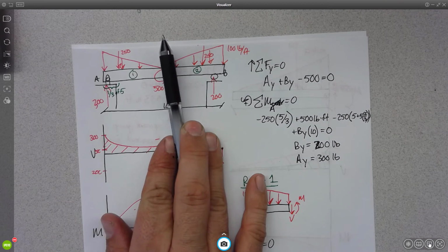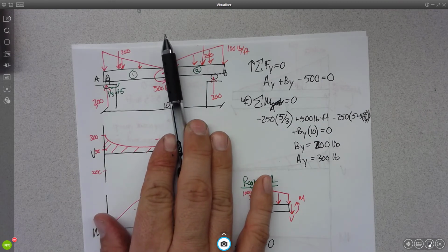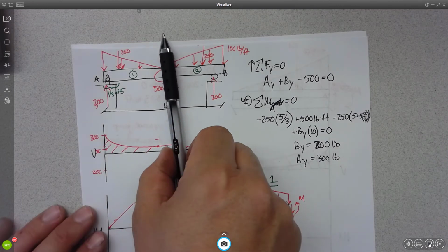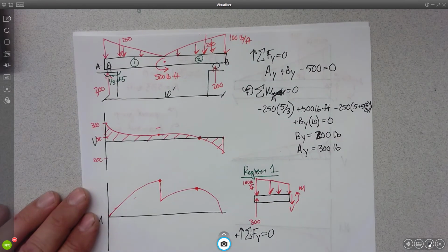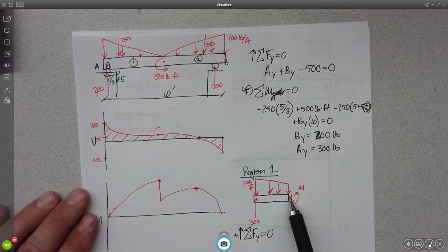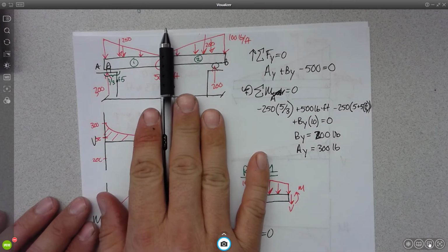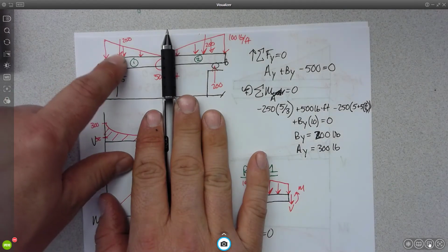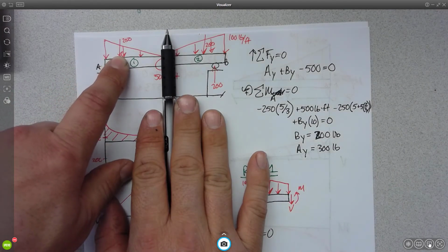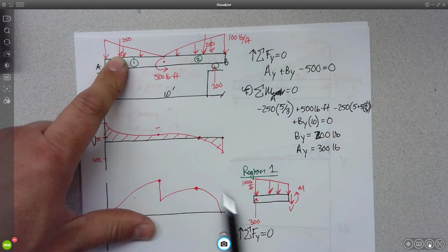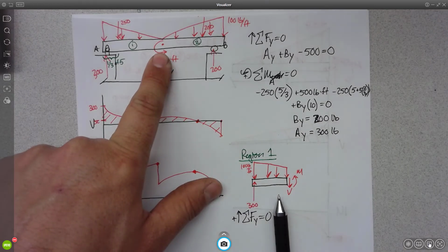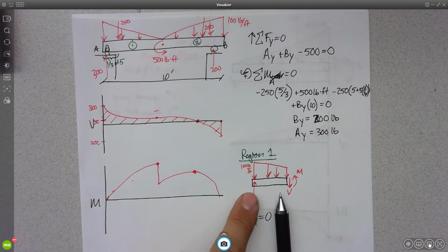Can't you find that if you slice it? Wouldn't it still apply? Because that whole area is X. No, that would not work. Let me show you why. Is this a triangle? So the question is, wouldn't it still work if I sliced it here to write the equation? No. I'm guessing what you want to do is say, well, it's always 1/3, 2/3, right? But if my slice is anywhere besides right here, is it 1/3, 2/3? It's not. I have a trapezoid that I have to deal with.